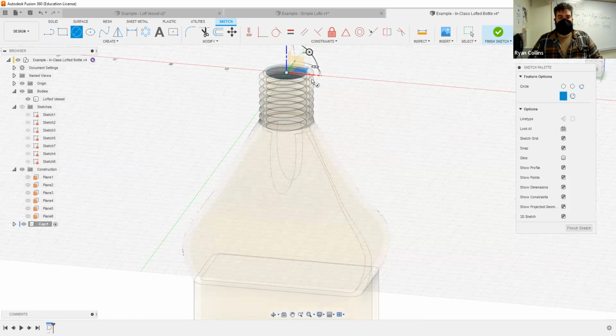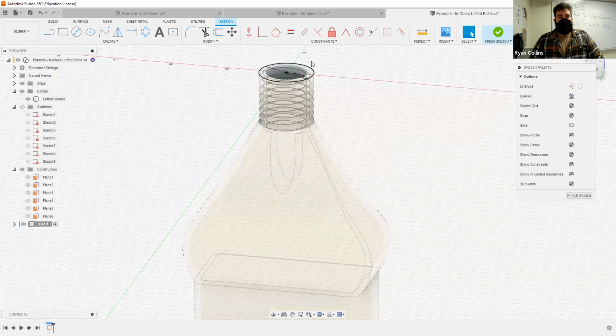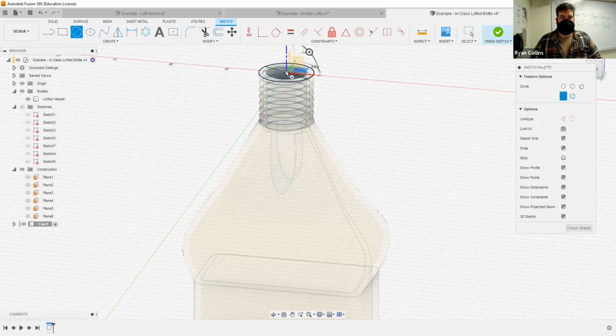center circle, drawing outward. Now, I can either create this 24 millimeters there, and I do need to make this larger, or I can do an extrusion with sketches. So I'm just going to show you the sketch way, and then the cylinder way. Now I do need to make a wall. Basically, this is going to be the innermost dimension, because this is aping this cylinder here that is threaded. So I need to make another circle right there, and right on top, right in the center.